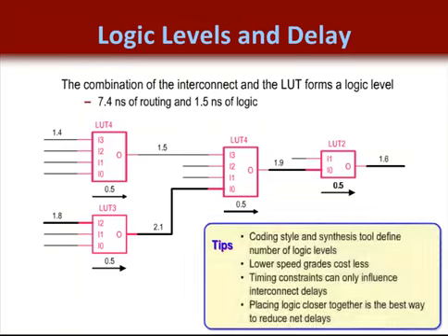The delay associated with the LUT is also very small, less than 0.5 nanoseconds typically. However, at the design level, it can appear that performance is highly variable, and you should appreciate what causes this to happen. The number of LUTs you have in series may be high, and thus the total delay on a critical path may be too long. The routing delays with the newest devices are nearly equivalent to LUT delays, not quite as in the case of this example. In fact, many of us use this way of estimating timing.